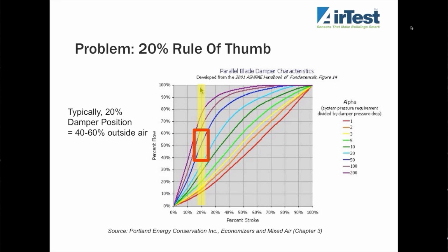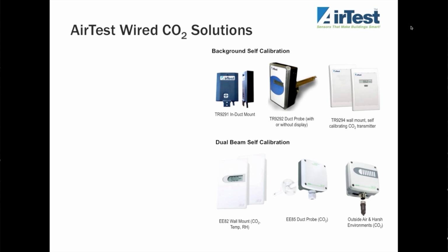That puts a great burden on the energy costs of the building, and actually in many cases means perhaps in very cold times or very hot, humid times, it may be difficult to control comfort in the building. So the key here is to have some sort of measurable feedback like CO2 that allows you to bring in just the right amount of fresh air.